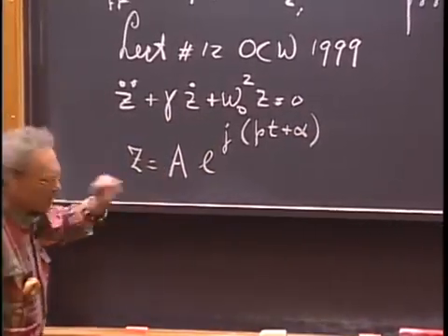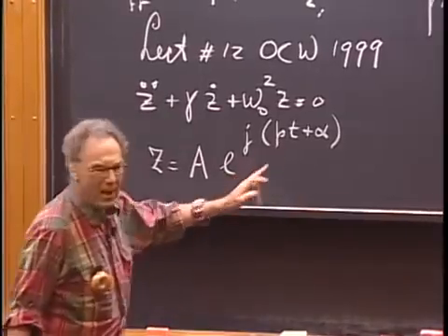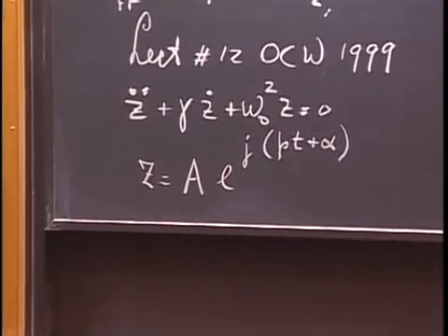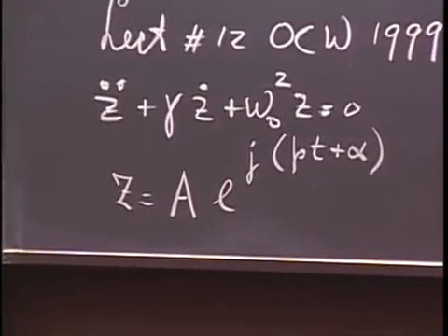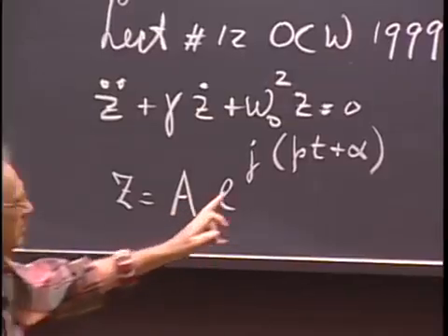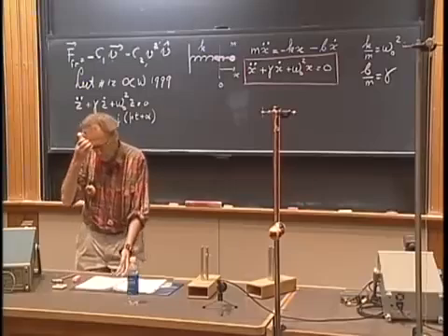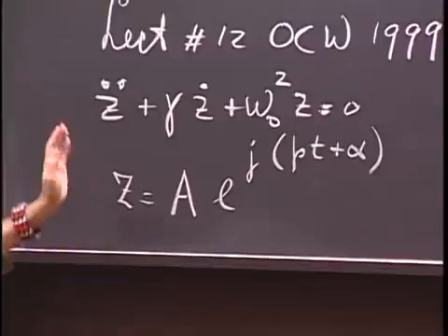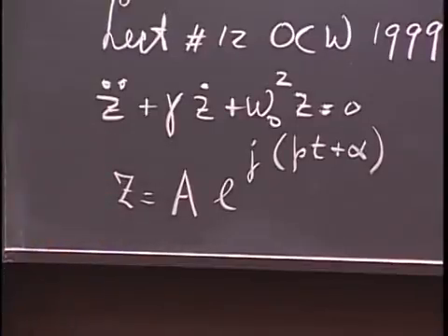Now clearly this has the smell of an amplitude, and this here has the smell of a frequency. Anything e to the power j pt has the smell of a frequency. But you will see that you're in for a surprise with this p. Once we have found a proper solution to z, we take the real part and we are in business. Then we go back to x.